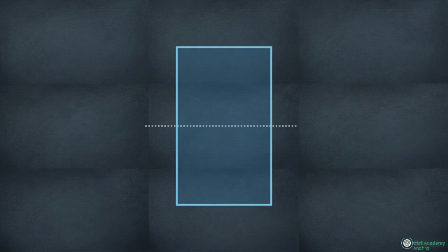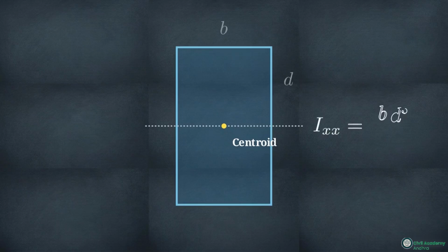This diagram displays a 2D cross-section of a rectangle with a horizontal x-axis drawn exactly through its geometric center, known as the centroid. For any standard shape, the lowest possible moment of inertia always occurs at this exact center point. For a rectangle, the baseline formula for this centroidal axis is width times depth cubed, divided by 12.